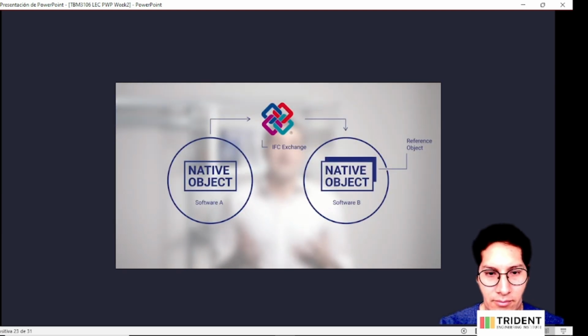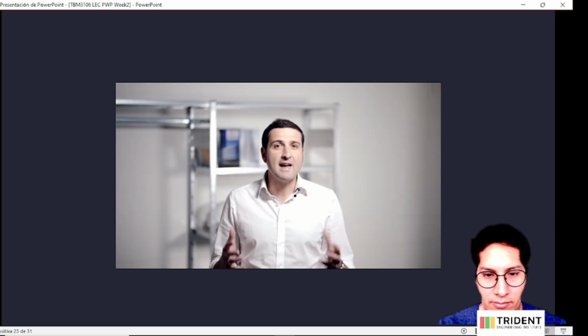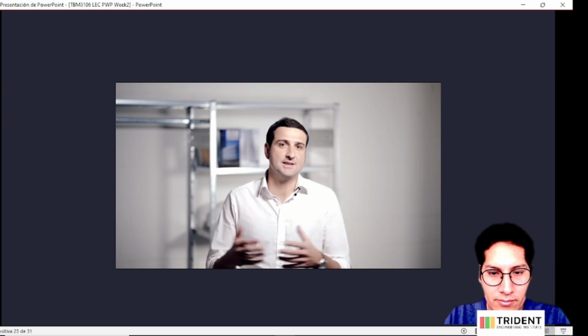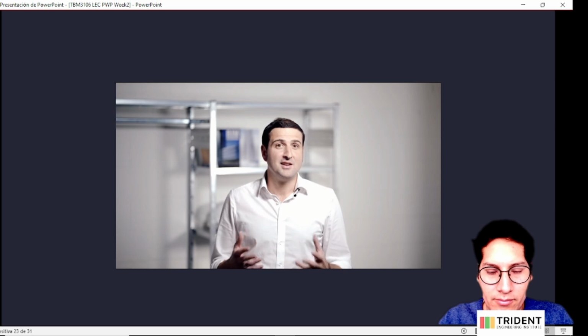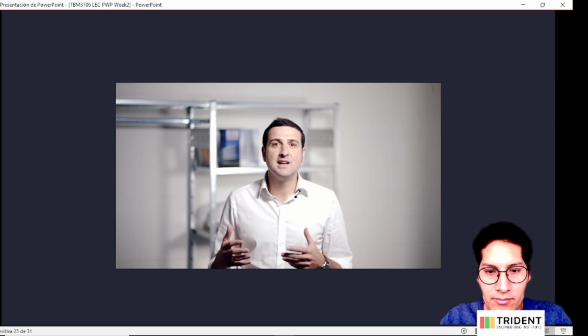A typical IFC workflow could be the following. An architect creates their design model and exports an IFC version to share with, for example, the HVAC engineer. The HVAC engineer can reference this file into their own software and use this for coordination. More than that, the engineer can also use the IFC model as a basis for analysis, for example energy analysis, which is pretty impressive. The IFC transports enough information for the simulation software to read and analyse the spaces in the referenced model.